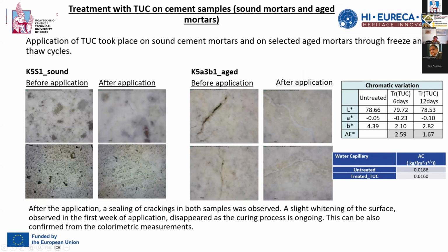A concrete that was deteriorated and aged with the freeze-thaw application, and the creation of those cracks, you may see that after the application the treatment shows a complete filling of these cracks, and not only that, but a self-healing effect in which more carbonated structures were produced after some time passed, filling those cracks that were produced.